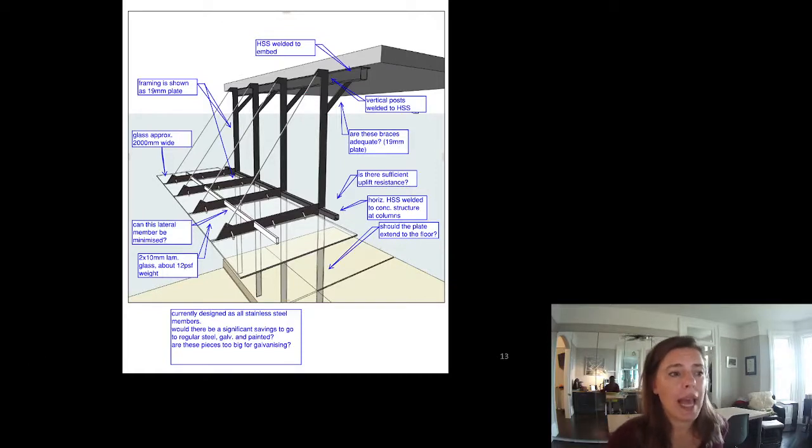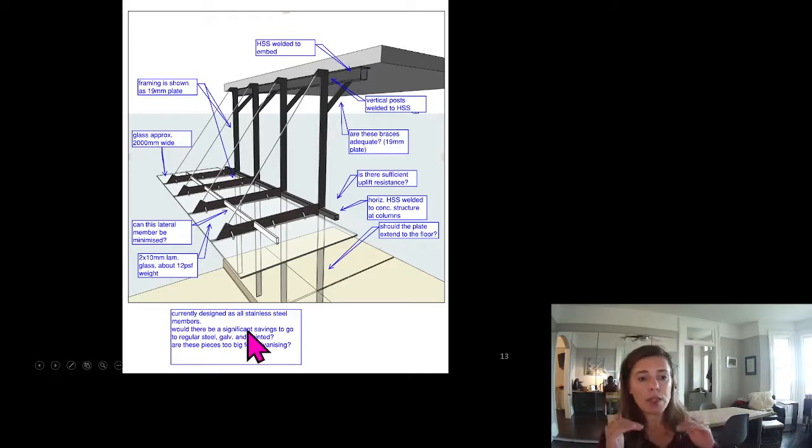But don't forget wind, we have uplift we have to deal with. And if that canopy is not very heavy, when the wind blows up on the canopy, we don't get to assume there's snow load up there, and we actually reduce the dead load some. So when we think about that, you can imagine that blowing upward and that canopy cable goes slack. It's not doing anything for us, meaning we still need a moment connection here for the canopy when there's wind blowing upwards on it.